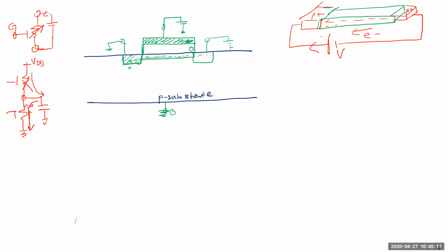Okay, how about Chandan? What do you think? So I didn't get your question. Okay, go back to metal. Will it conduct or not conduct? Yes, sir. It will conduct. Okay, and why will it conduct? It has more free electrons compared to an N-type, and also the work function is less, so it's easier to take out electrons from the metal too.